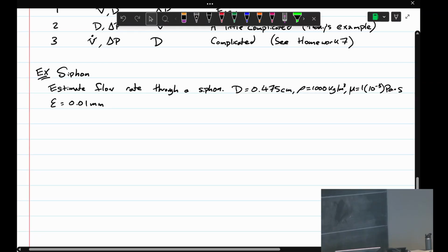Does the siphon work if you don't have any atmosphere, even if you don't have a continuous flow? Yeah, the atmospheric pressure doesn't actually matter at all. We'll see in the analysis. It's all about the gravity. The reason atmospheric pressure doesn't matter is because the top of this reservoir will be considered 1 point in our Bernoulli's equation, and the discharge point of the tubing is another point in our Bernoulli's equation. If you assume both of those points are at atmospheric pressure, that cancels out in the equation.